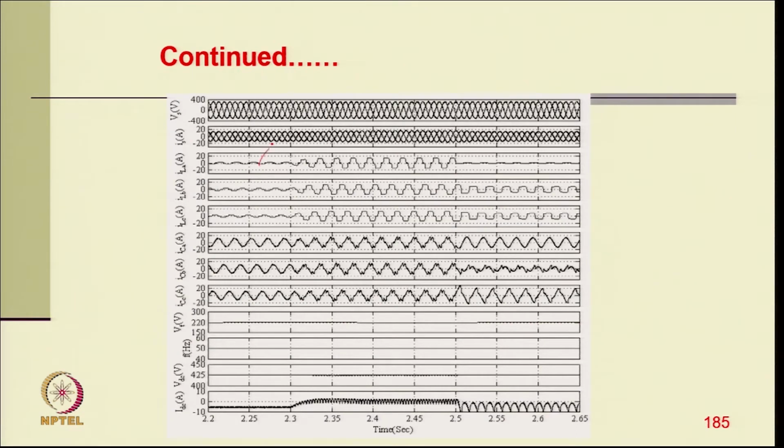So, initially low nonlinear load, then nonlinear load is increased, then load unbalancing is there, but generator current remains between 80 to 100%. If load is less, and the compensator is providing load balancing as well as harmonic elimination in this case, and that is the reason generator current remains balanced and sinusoidal. And voltage is also regulated, and you can see the battery accordingly getting charged and discharged depending upon the load condition.